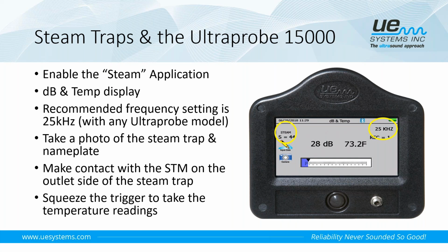We want to make sure that our frequency setting is set to 25 kilohertz, so that you see that in the top right-hand corner of the display from the UltraProbe.